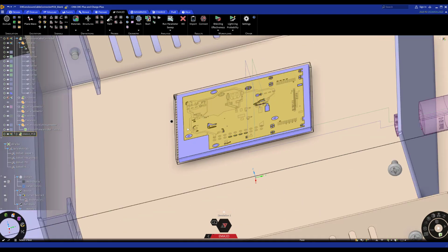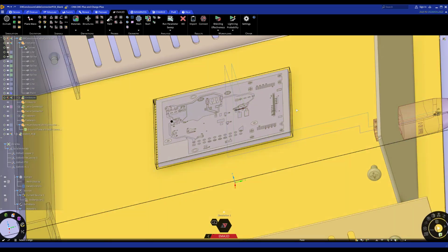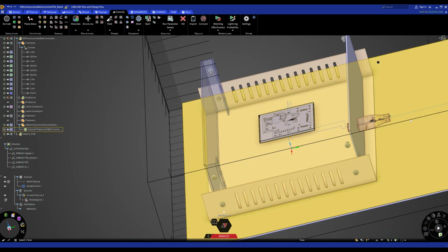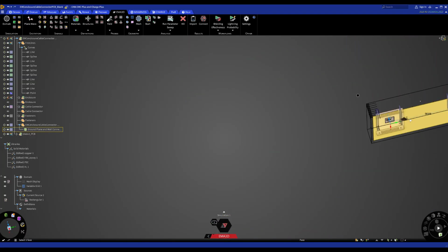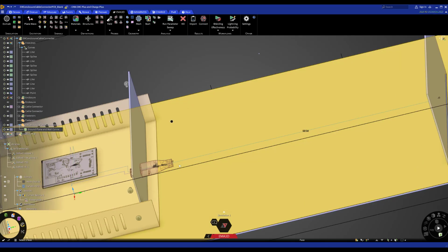Now, since we have two different domains with two different step sizes, this can create an issue for the MHARNESS. The reason for that is, for this domain, the smaller step size will need to be gradually changing as you exit from this domain to the larger domain. So the step size around the MHARNESS will not be uniform, and that can create an issue with solving the MHARNESS. To do that, we want to define another variable grid to ensure that we have a constant step size along the route of the MHARNESS.